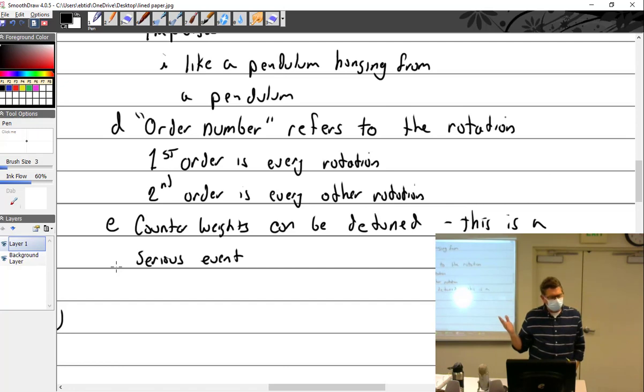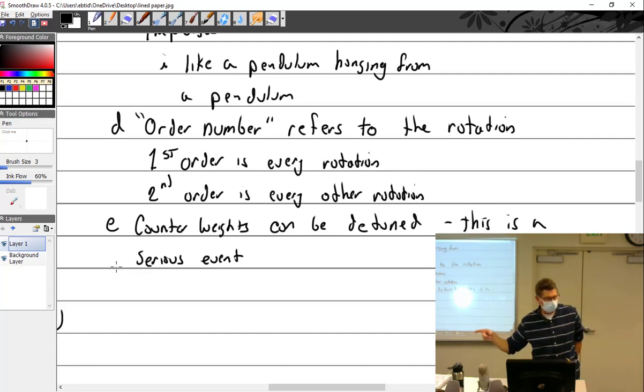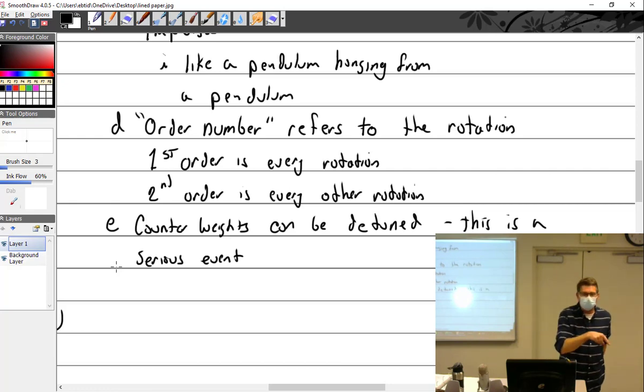I remember I was at a seminar one time about a company that does vibration analysis on helicopters. It's a program they're selling, or I don't know if it was part of the helicopter, but after every flight or every so many flights, it would data link to the manufacturer with all the statistics of the vibration analysis. They could look up and say, okay, you've got a vibration at this harmonic. That means you have a tail rotor bearing, or a bearing going out in this transmission.